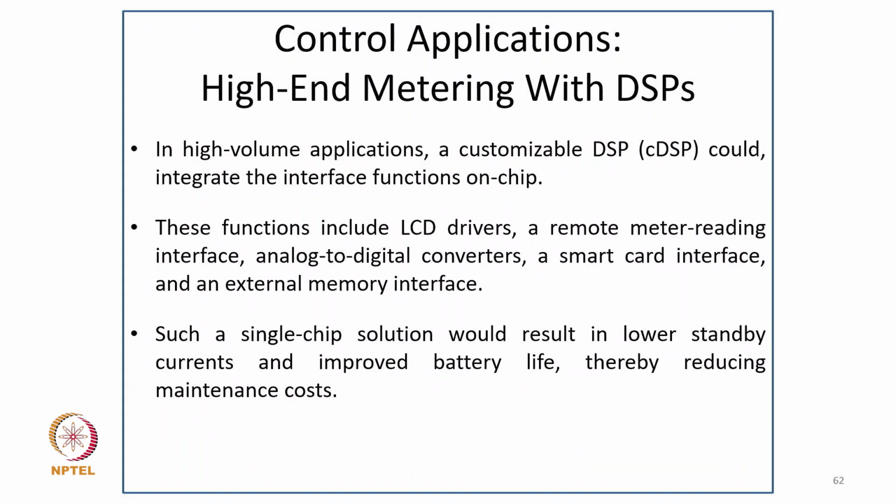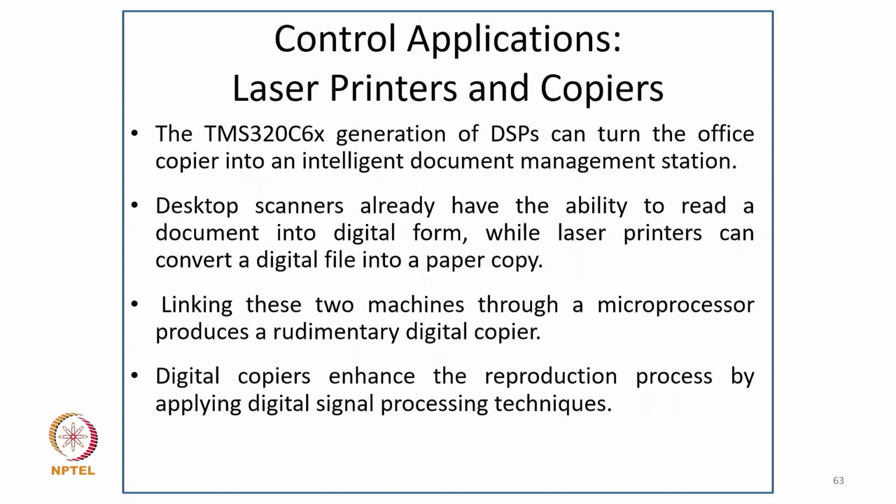So in high volume applications, a customizable DSP, CDSP, could integrate the interface functions on-chip, and these functions include the LCD drivers, a remote meter reading interface, analog to digital converters, a smart card interface, and an external memory interface. And such a single chip solution would result in low standby currents and improved battery life, thereby reducing maintenance cost.